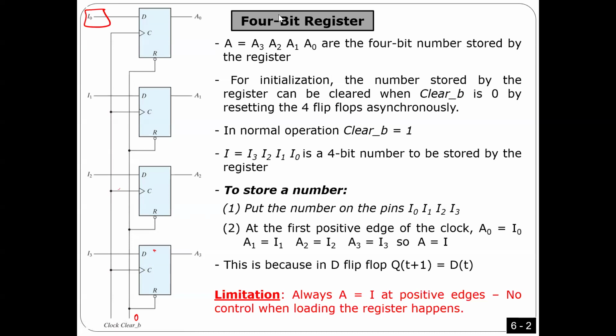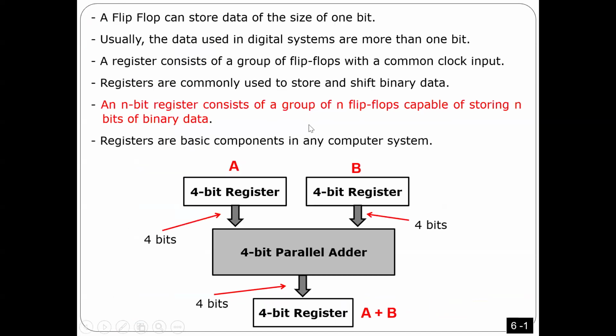Any question? Do you understand what I mean by register? How do we make it? We make it out of D flip-flops, as you see here. And why do we use it? We use it a lot. If you look at any microcontroller, microprocessor, any digital system, the system is full of registers. Because if you have an arithmetic unit like a multiplier, a divider, whatever the system is, I need to store the output somewhere. Also, I need to store the input somewhere. That's why we use registers.